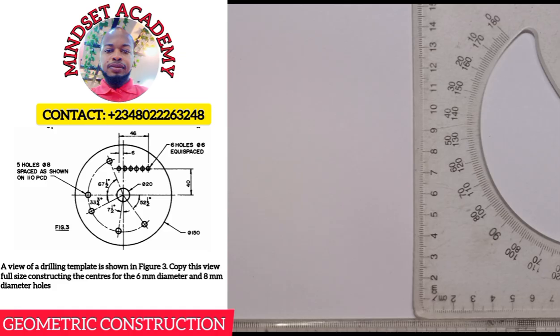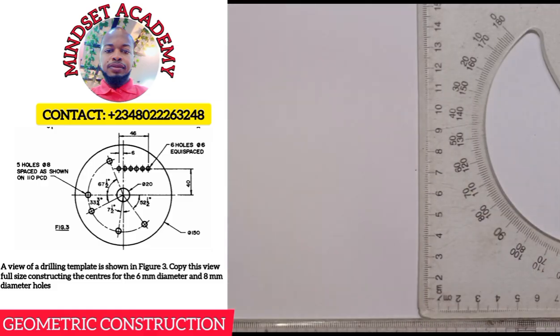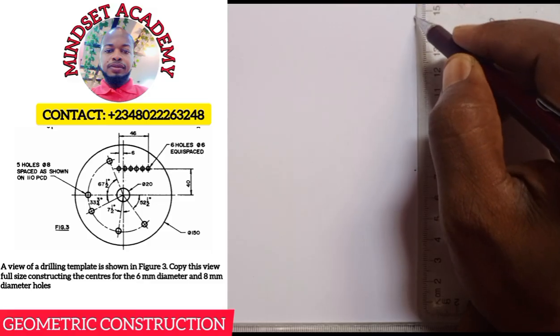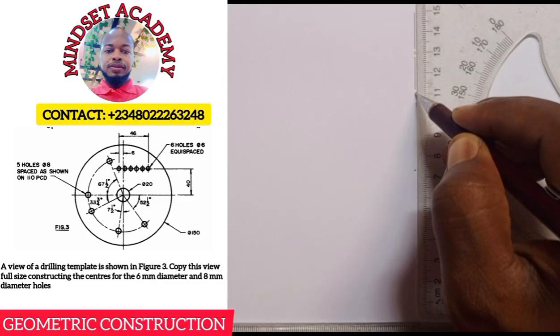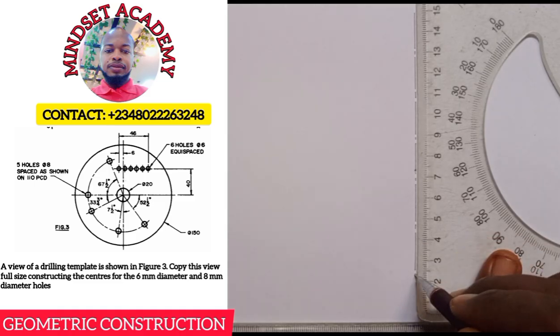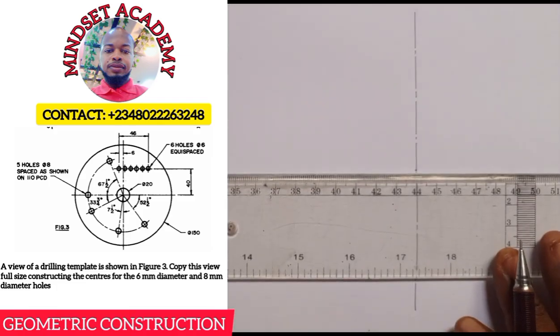So the first thing you do when you see a question like this, especially when it involves a circle, you draw your center lines. So I can push this from here to be my center line, any given line of your choice. So we have long, short, long, short, long, short, long, short, long, short, just like that. You end with long. Then you do the horizontal one too.